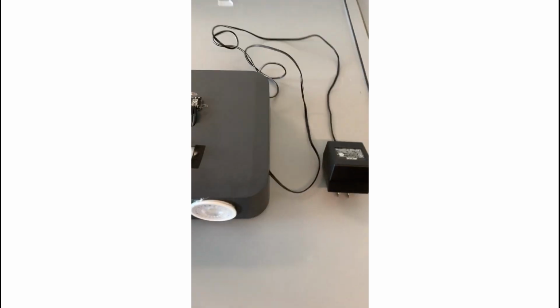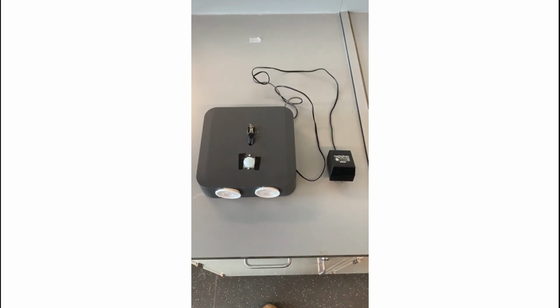With the final product done, all that was left was to verify it worked as expected. As you can see in this demo, with the LDR sensor exposed to the light, motion doesn't flip the lights on. However, when I cover that sensor up to simulate darkness, my motion begins tripping the relay and turning the lights on.